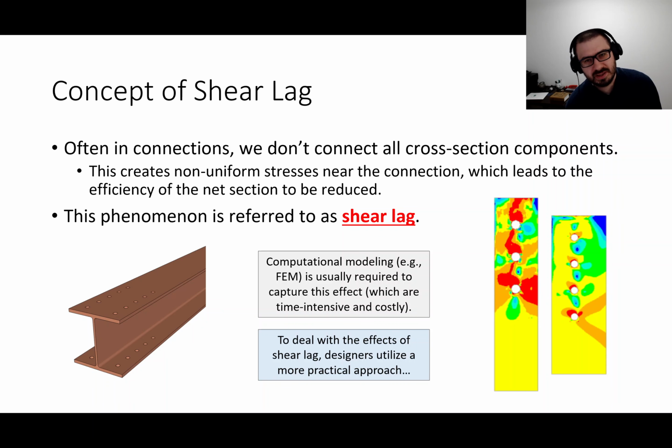Mechanistic equations, while valuable, tend to be based on assumptions. And sometimes those assumptions break down. A good example is this right here. Sigma equals P over A is great, but we're assuming a uniform stress distribution. That is not happening here. This stress distribution is a mess, okay? So we need to be able to handle that. And that's where an empirical expression comes in.